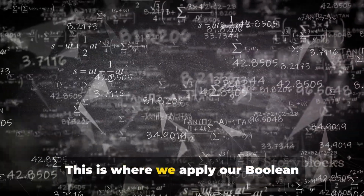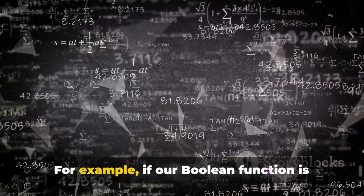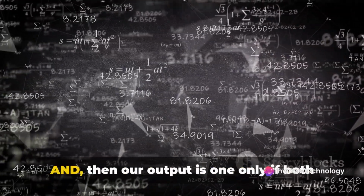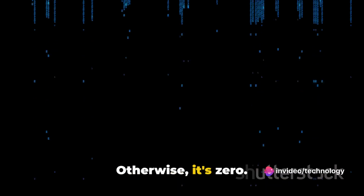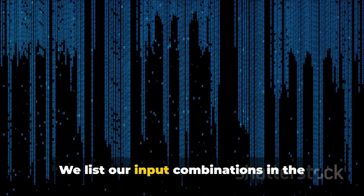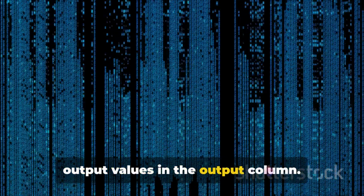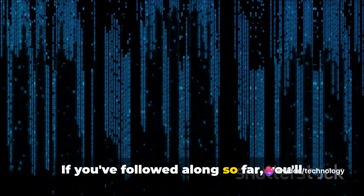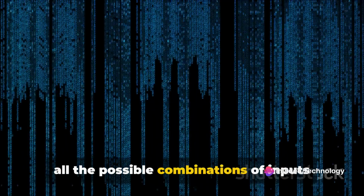Once we have our inputs and their possible combinations, we move on to the fun part, evaluating the Boolean expression. This is where we apply our Boolean function to each combination of input values. For example, if our Boolean function is AND, then our output is 1 only if both our inputs are 1. Otherwise, it's 0. Now we're ready to fill in our truth table. We list our input combinations in the input columns and their corresponding output values in the output column.